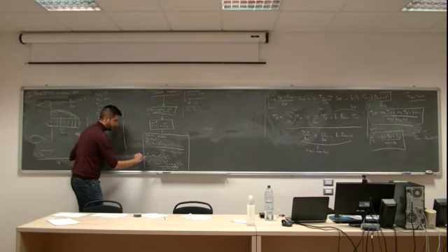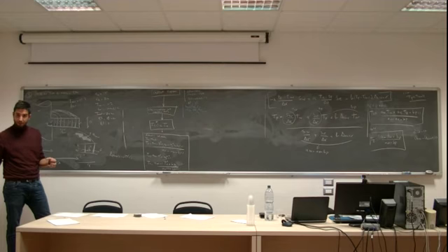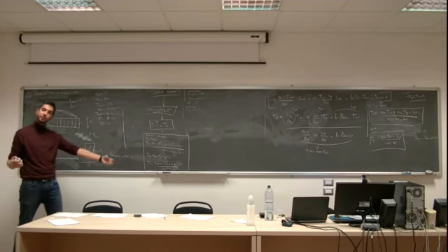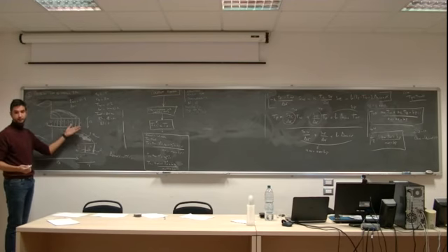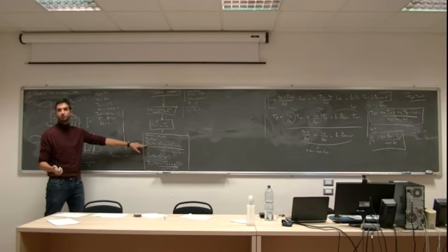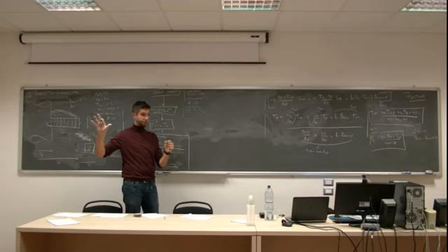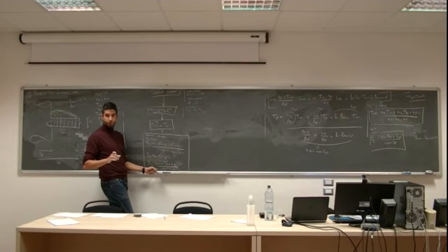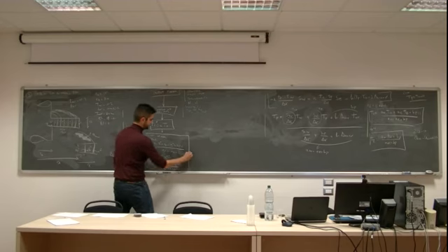Now, what do we get? We compute T0, T1, T2, T3, 4, 6, 7. Now we have a map of temperatures which are solutions, and a map of temperatures which are assumptions. I assumed that everything was at 70, but I went here and got T1 equal to 62. But I assumed it was 70. Now I have two maps. Do you follow me? A map of solutions after passing through the equations, and a map of what I assumed.